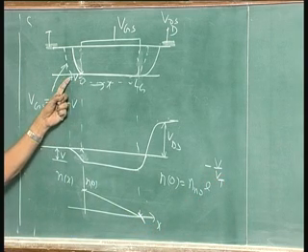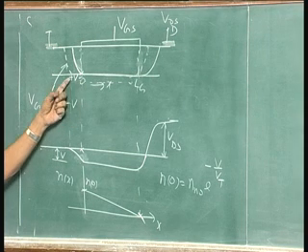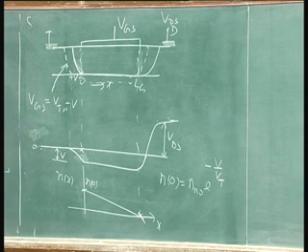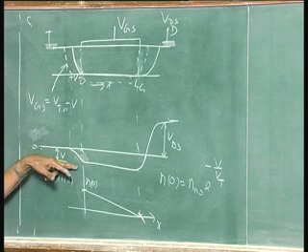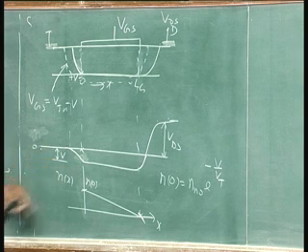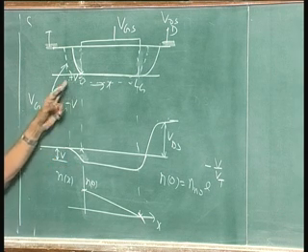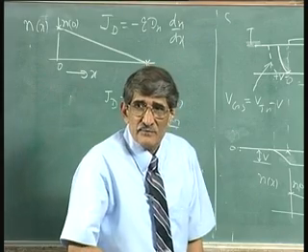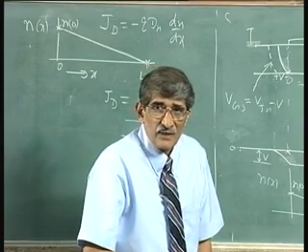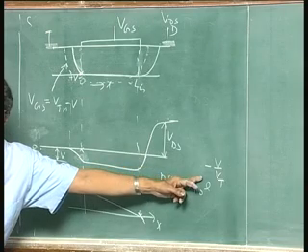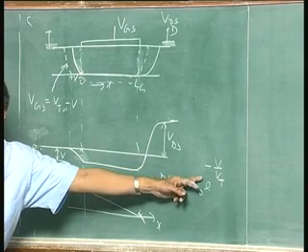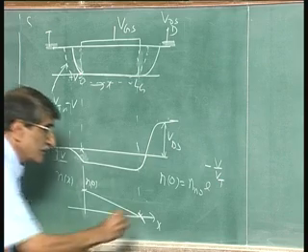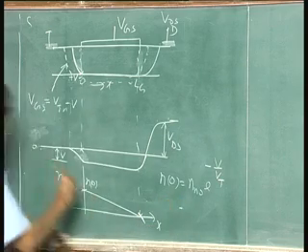When you move from positive to negative or 0 to negative potential, it is a potential barrier to the electrons. I am plotting electrostatic potential. If you take the potential for the electrons, it finds it difficult to move towards the negative portion. So, that is why that carrier concentration will be lower by an amount related to the voltage. This is the Boltzmann law. So, now what is this quantity V?